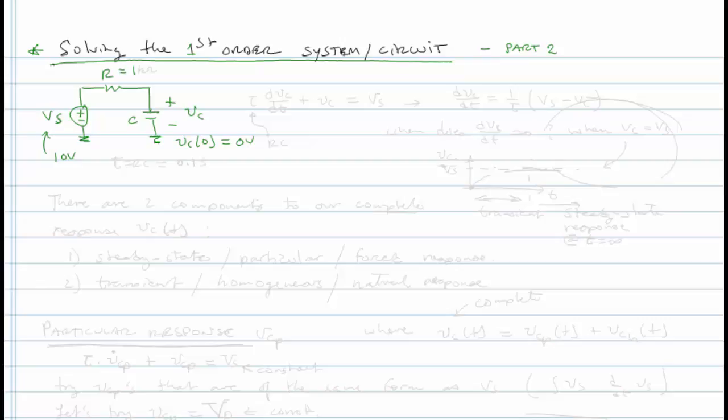So we can say this is 1K, and so that means we'd have a 10 milliamp current flowing into the capacitor, which means that the capacitor will charge, right? The capacitor will charge, the voltage will increase on it. We saw this from the state equation.